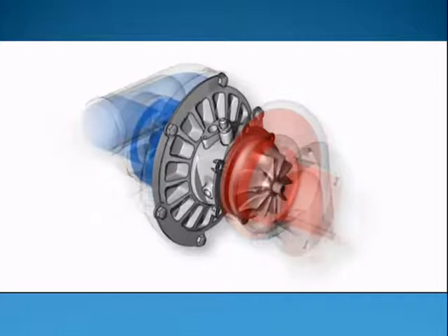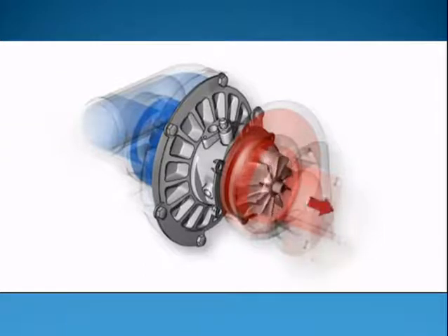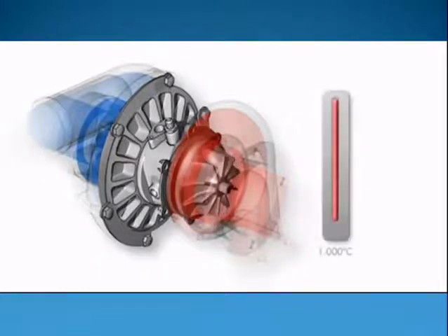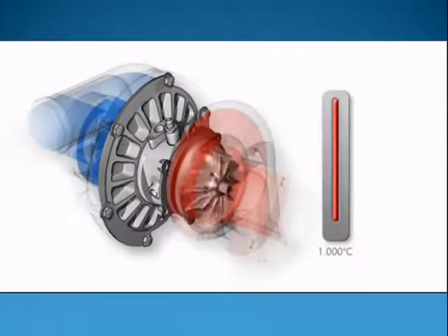Design and production of an exhaust gas turbocharger necessitate very good engineering. On today's exhaust gas turbochargers, temperatures of over 1000 degrees Celsius are achieved at the turbine side, and the exhaust gas turbochargers operate at tremendous speeds of rotation of up to 300,000 revolutions per minute. This means that they make stringent demands in respect of materials, manufacturing tolerances, and bearing assemblies.